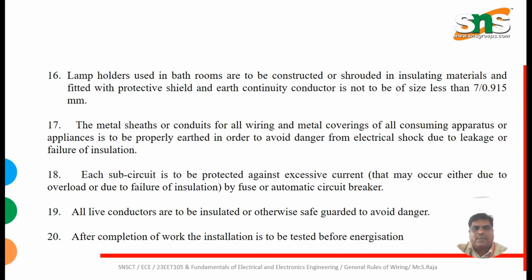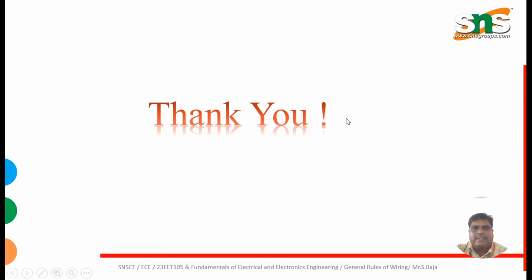Each subcircuit is to be protected against excessive current by fuse or automatic circuit breaker. All live conductors are to be insulated or otherwise safeguarded to avoid danger. After completion of work, the installation is to be tested before energization.